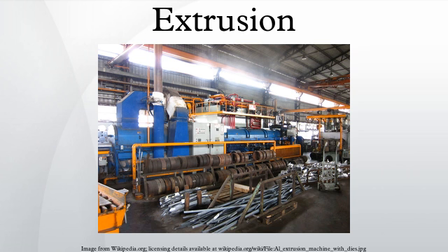There is less of a tendency for extrusions to crack because there is no heat formed from friction. The container liner will last longer due to less wear. The billet is used more uniformly, so extrusion defects and coarse-grained peripheral zones are less likely.